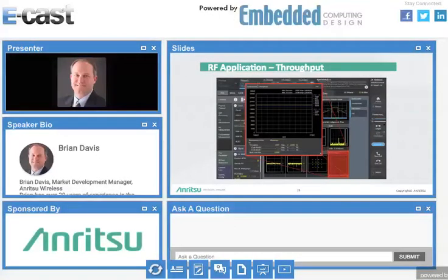And then finally, bringing all that stuff together, right? It's all going to affect your throughput. So we've got a nice MAC layer throughput. This can be separated out into uplink and downlink. So uplink, you've got supplemental carriers there. In this case, we've got the primary carrier and then 4 supplemental carriers. So you can get the MAC layer throughput of each one of those individually plotted out there. And then your uplink as well, so your primary and secondary. You can break those all out too in a SISO mode or a MIMO mode as well.